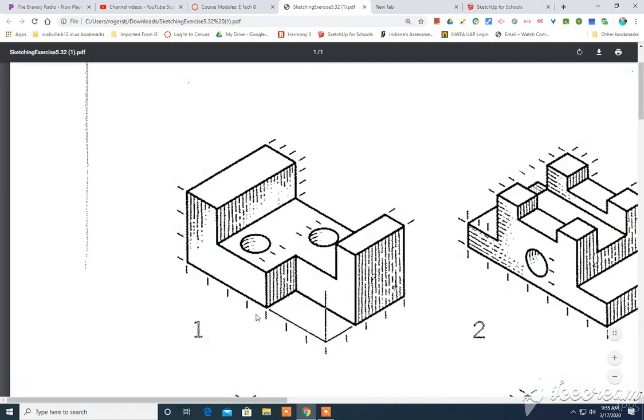So I note its dimensions here in length from left to right. I've got 1 half, 2 halves, 3 halves. That's 1.5 inches. And then this part here needs to be 3/4 of an inch deep, and I know that because of these tick marks right here, 1/4, 2/4, 3/4. So what I'm going to do